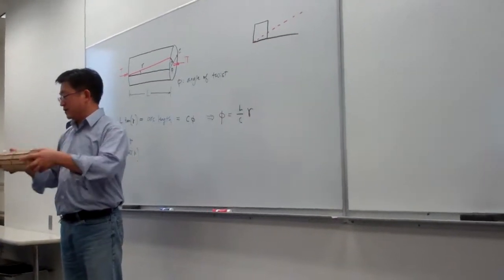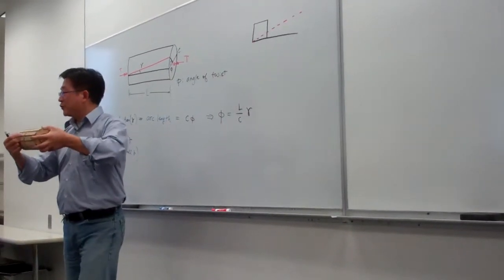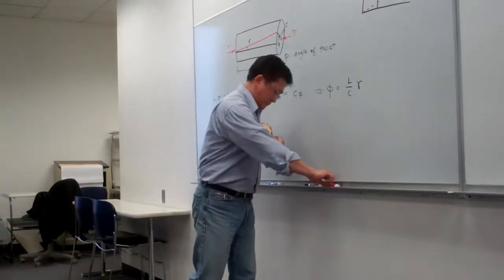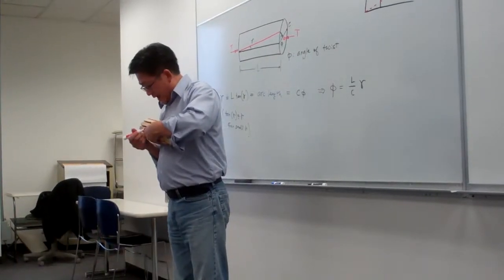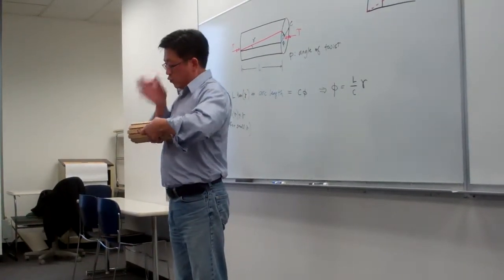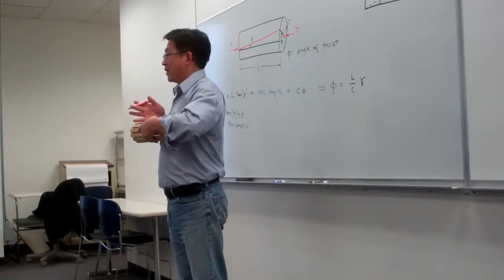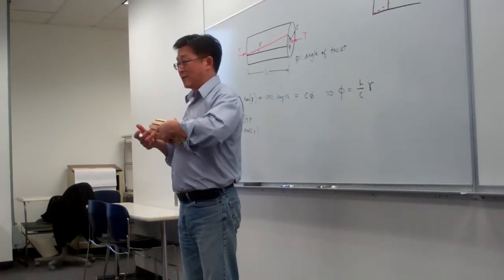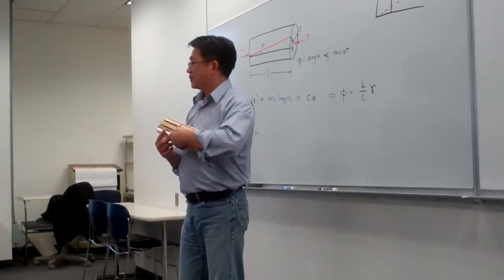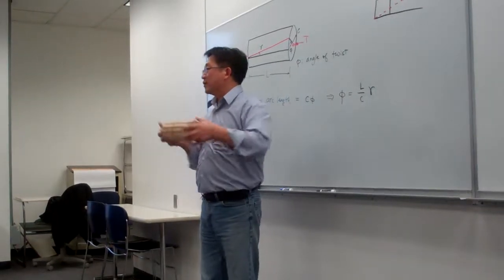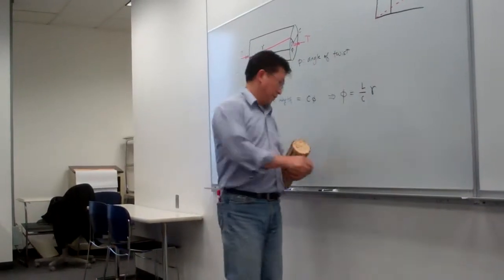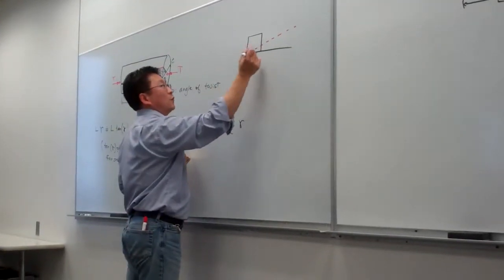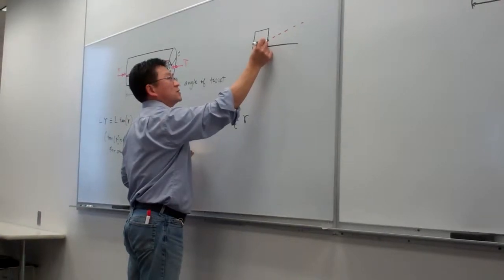Once this cube deforms, this side basically is falling onto one normal cut. So this side is part of the cross section. The very first assumption is this: due to the small deformations, all the particles on one cross section will move on the same cross section.